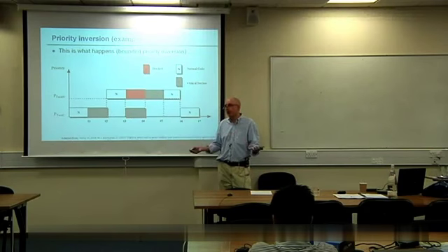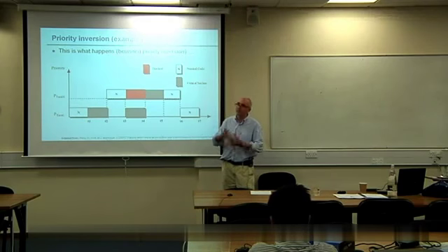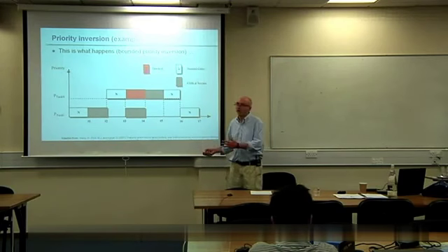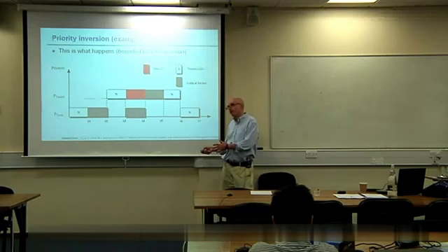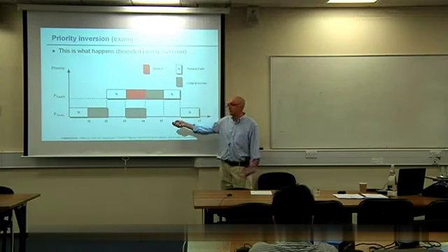So essentially, we've got to store the current state of this task, which typically means stack contents of some kind, where we are in that task, what the return address is, values of any local variables, etc. All have to be stored, and they have to be stored somewhere in memory. That process is going to take time, and it's going to require memory.